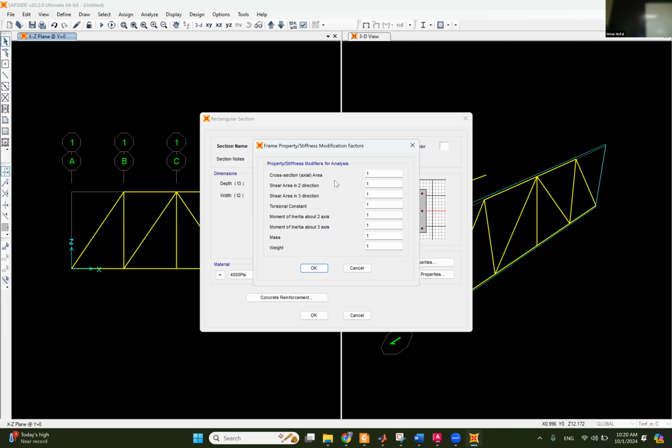Okay. And actually, you know what? Sometimes, I'm not sure if you guys face these problems or not, in structure analysis and advanced ones, you have a member, and I don't give you a cross section. I tell you that this section has stiffness EI and this one is 2 EI. That means that this is double the stiffness. So maybe you assume one cross section, and double the stiffness for one of them, rather than developing a section that has I and trying to find out how to make it 2I. So sometimes we multiply the stiffness by 2. Okay.